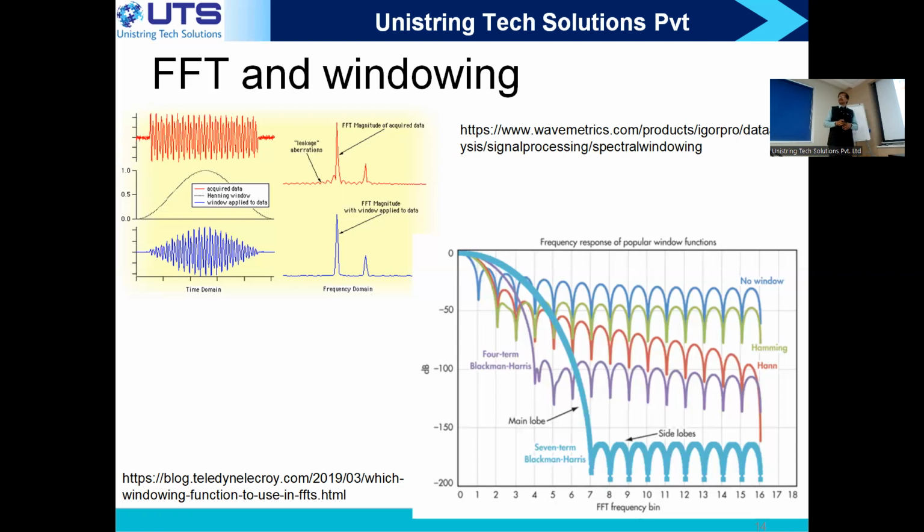Why is this so important in products like radar? In radar, let's assume there is a target coming with some very high velocity, some 100 meters per second. That target has a stronger echo. When you compute its frequency, its energy gets leaked into the other bins, because in Doppler the frequency and the velocity are one and the same; you measure velocity by measuring the frequency.